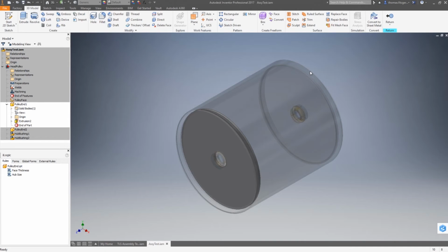You know, try not to use too many patterns, feature patterns. Those have a tendency to bloat a file, unless of course you're using some level of efficiency with it. Save your fillets and chamfers for last if at all possible. Try to do the bulk of your model building towards the beginning, and then refine or start adding that level of detail as you progress through the model development.